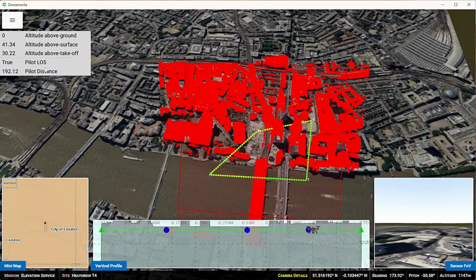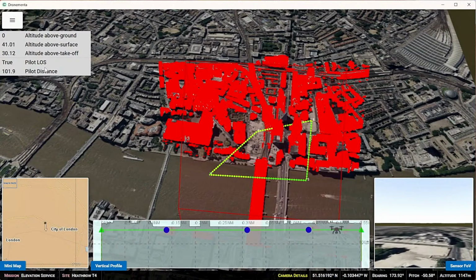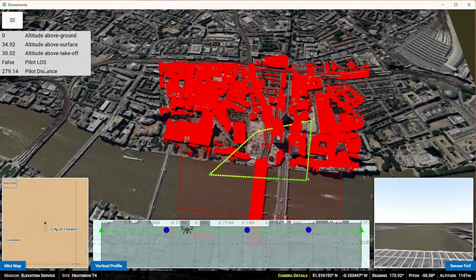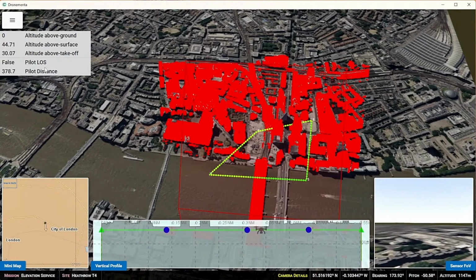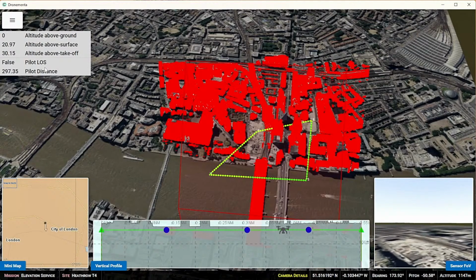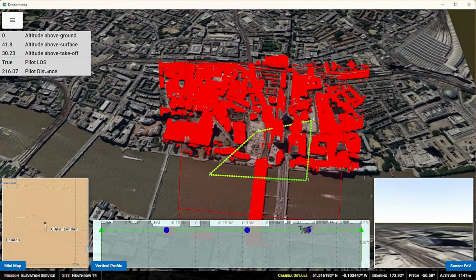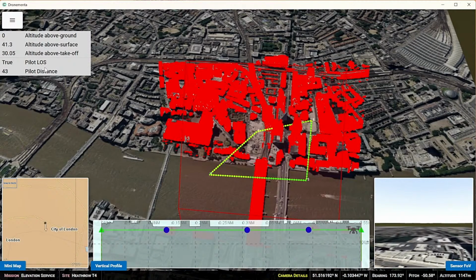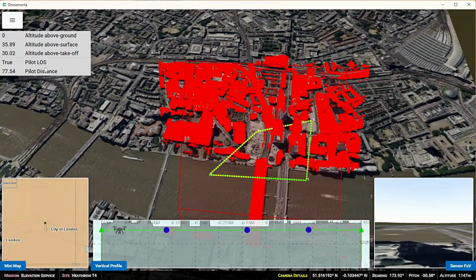As the drone is updating its position, we are calling the API in AWS and asking if the pilot can see the drone from that location. In the same call, you can ask for just the line of sight, or you can ask for a vector line of sight from point to a point, a single point. So in this example, we're actually asking for the vector, which is providing you yes or no, you can see it, as well as the distance, the bearing, and the pitch. So if you needed to point sensors to capture that information, or to point a camera at it, the API will also give you that position at the same time.